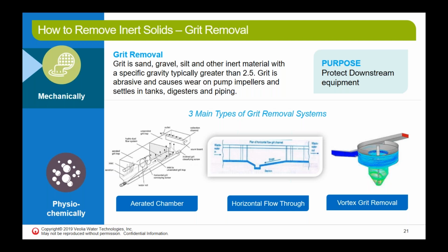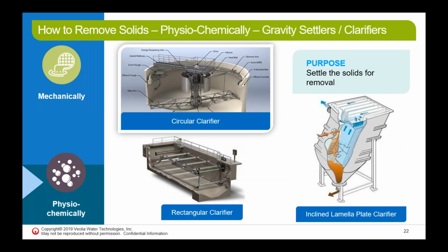And they're usually very small systems comparatively, because we want to utilize very little time and separate as much of the grit solids as possible. In the vortex systems, we rely on the centrifugal forces, so we apply a gentle centrifugal force that will push away the heavy solids to the sides while the lighter solids and the water continue flowing forward, and we accumulate the heavy solids on the bottom. Next slide, please.